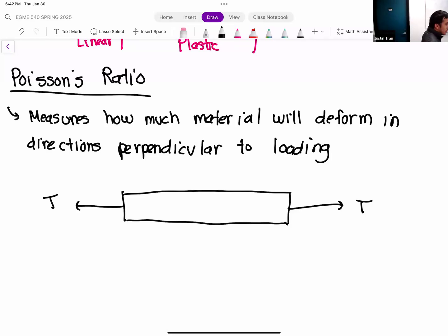If the tension is high enough, what we generally expect in this situation is that this rod should elongate. You should get some elongation on this side, and some elongation on this side. So the total length of that rod should increase by applying this tensile load. That makes sense. That's consistent with everything that we've discussed. You apply a load that applies stress. That stress causes strain, and that strain reflects how much the part is deformed.